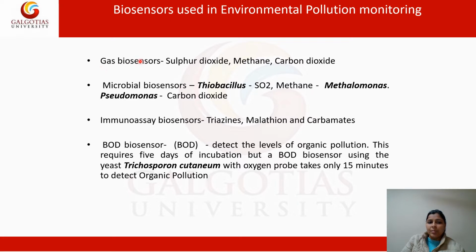We'll discuss some of the biosensors. One is the gas biosensor, used for detection of sulfur dioxide, methane, and carbon dioxide. Besides that, we have microbial biosensors, which are more specific. Next is immunoassay biosensors, used for triazines and carbamates. Then we have BOD sensors, which detect the level of organic pollution. The conventional method requires 5 days of incubation, but a BOD sensor using yeast with an oxygen probe can take only 15 minutes to detect organic pollution.